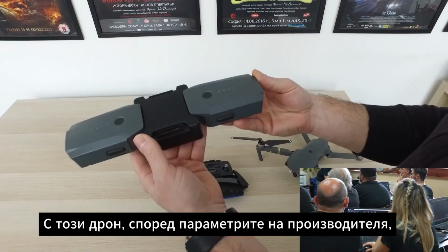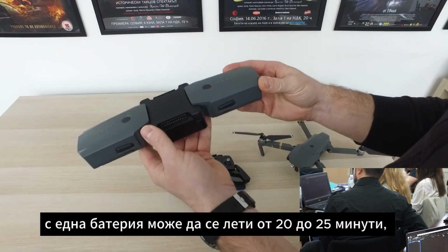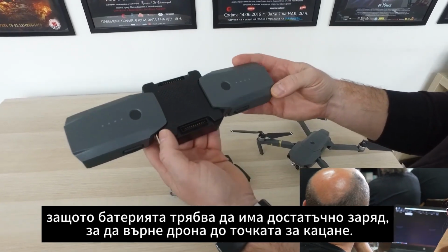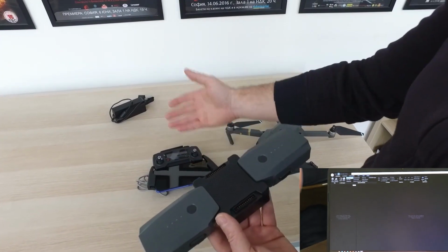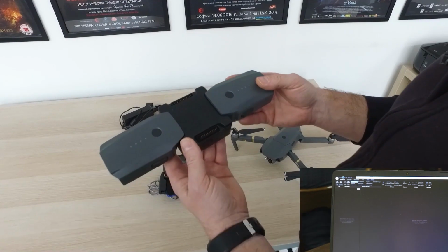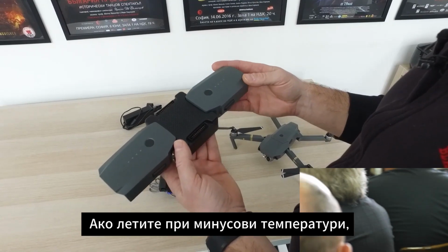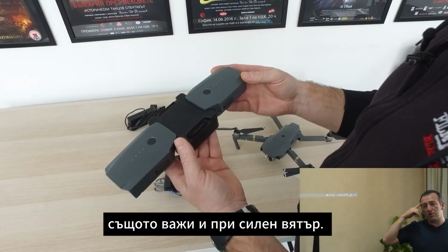With this drone, according to the manufacturer's parameters, one battery can be flown for 20 to 25 minutes, but we never allow ourselves to fly that long, because the battery must have a charge to return the drone to the landing point. On the mobile application you have information on how much charge is left on the battery. Also, the charge of the batteries depends on the weather conditions. If you fly in sub-zero temperatures, the charge of the batteries drops faster. The same is true in strong winds.